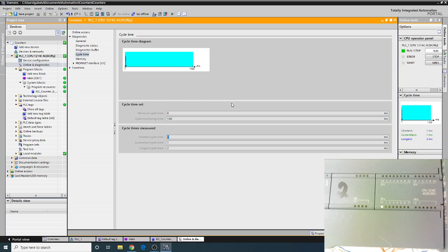But again, it means only 50 bottles can get counted through a sensor as long as they're consistently moving, which should still be plausible, but we could start pushing the limits here. So you can get what's called a high-speed counter.